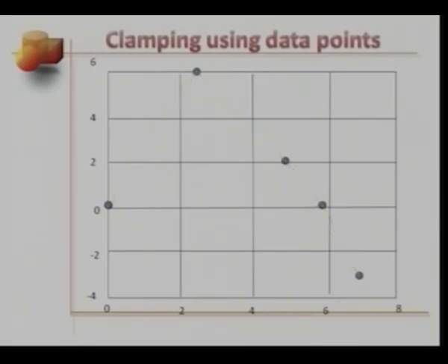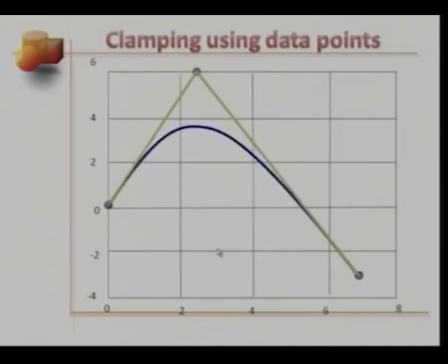Let's experiment further, and let's merge the last 3 control points together so as to raise the multiplicity of this design point by 3 as well. This is our polyline, and the curve in blue is the new B-spline curve. You would not be surprised that this passes through the last design point as well.